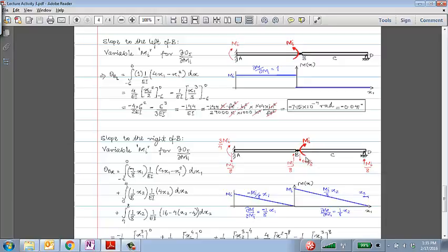And similarly for the right hand side, now the bending moment diagram is a little more interesting. On the right hand side, I'm applying a moment Mi, additional moment Mi. But on the left hand side, there is no moment because there is an internal hinge. So this moment will cause BCD to behave like a simply supported beam with an end moment at one point, right? So BCD would be behaving like a simply supported beam with an end moment, and we know that the diagram would look like that for such a beam.